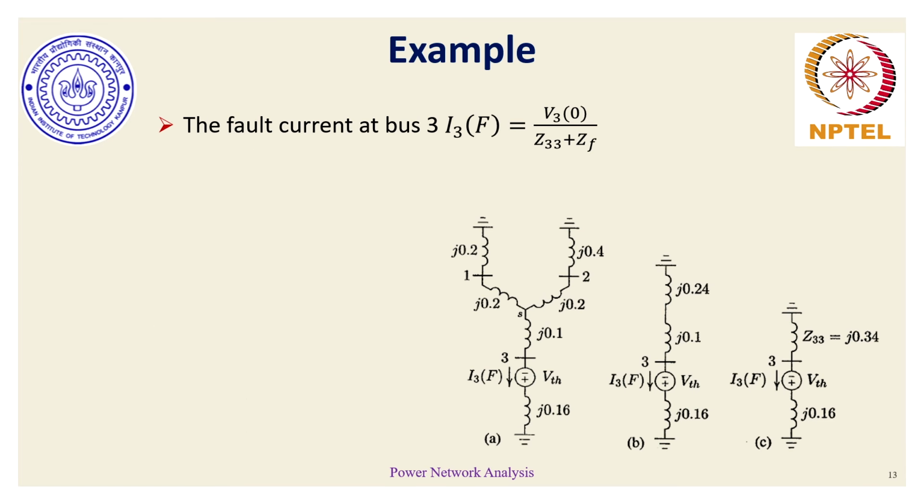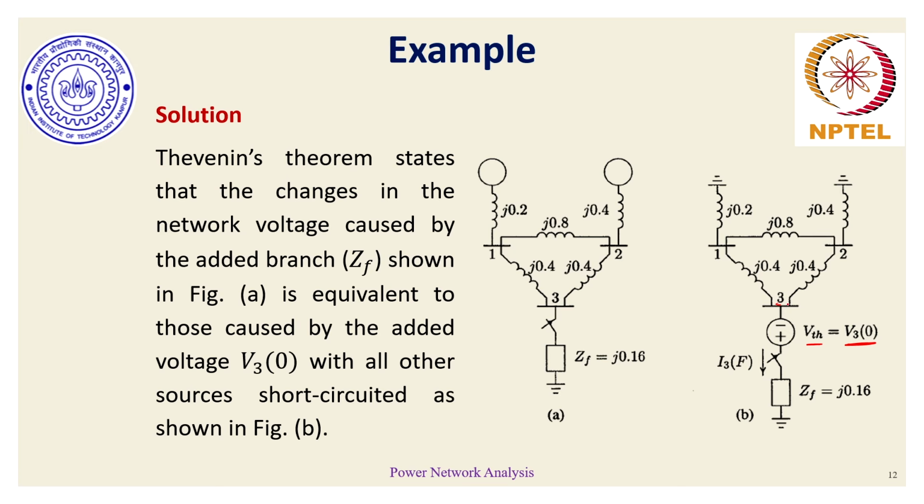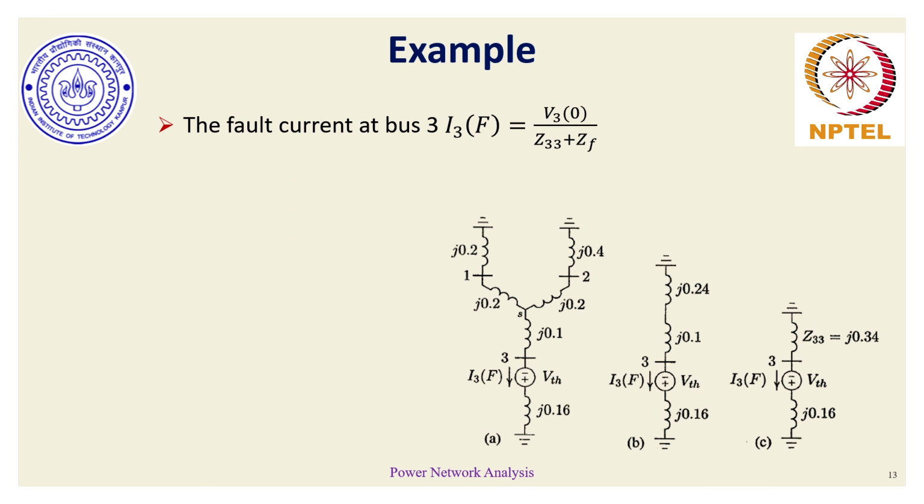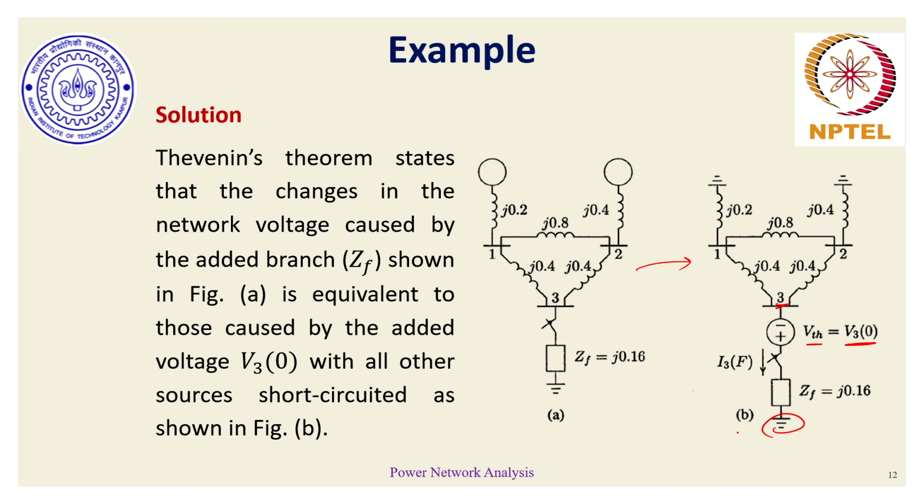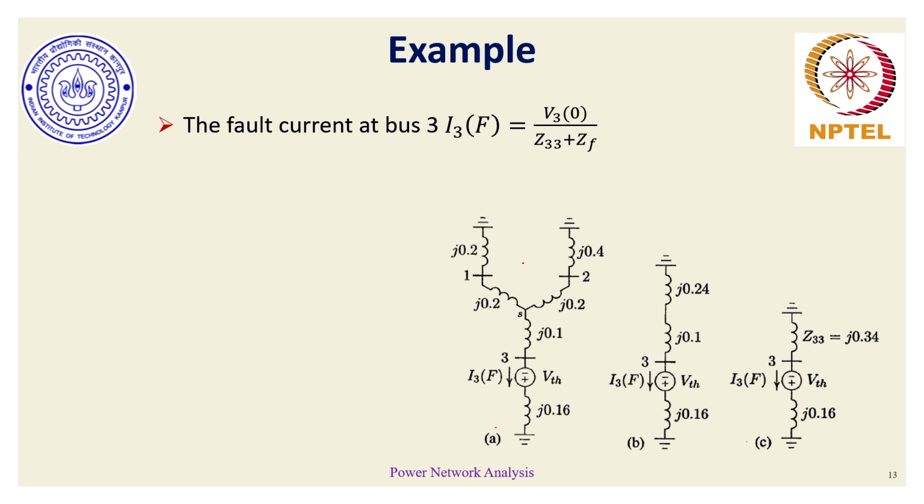To find the Thevenin impedance between bus 3 and bus K, the points across which the disturbance or fault has occurred, we can simplify this circuit, apply combinations of equivalent resistances, impedances, do delta-star, star-delta conversion, so that figure B here is redrawn as figure A with delta-star conversion applied. And here we see that between S and ground, there are two similar paths.